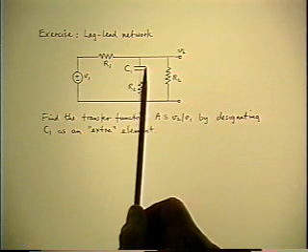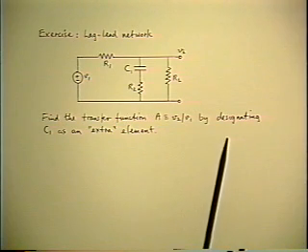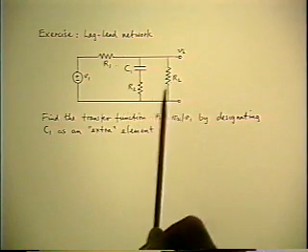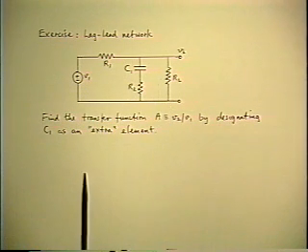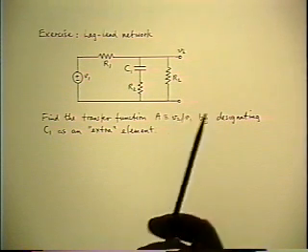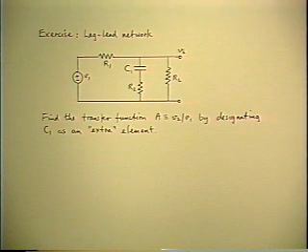On the other hand, if you replace the capacitor with a short, which you could equally well do, then the reference circuit is now the high frequency flat gain. And so the high frequency gain will come out in front as the reference, and the pole and the zero will come out inverted. So you have the choice which way to do it, and the choice is determined by which way you want the answer to come out.